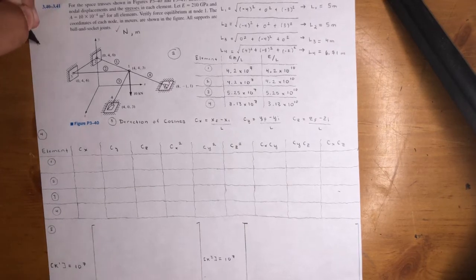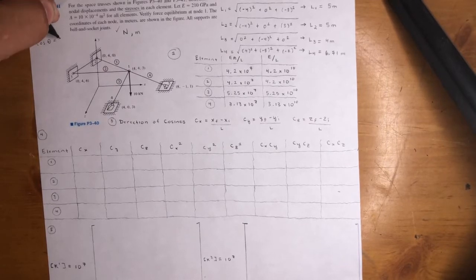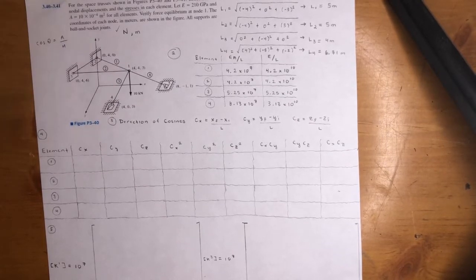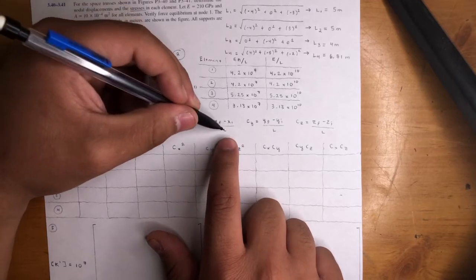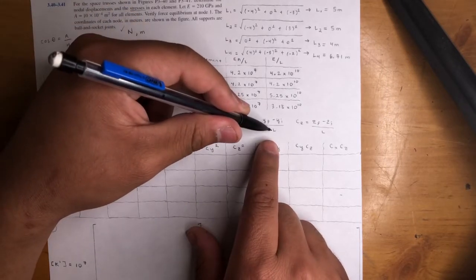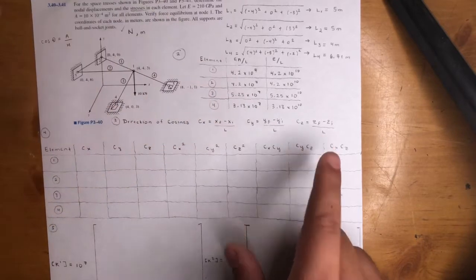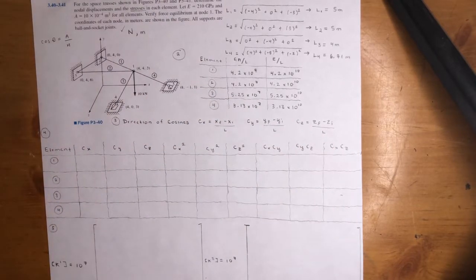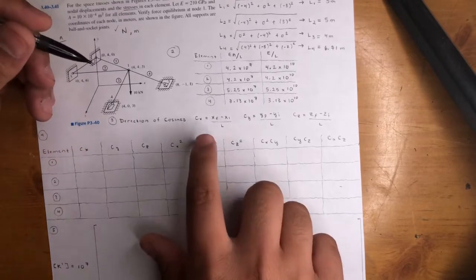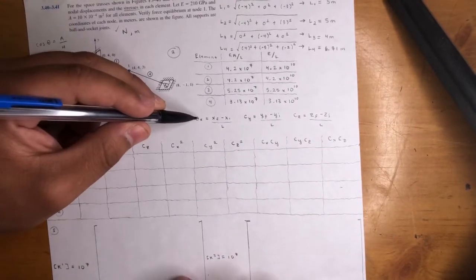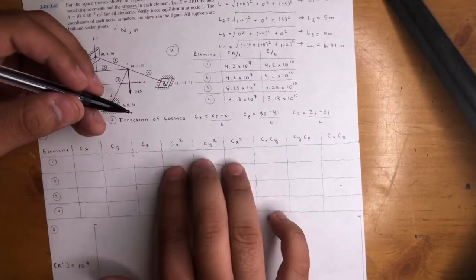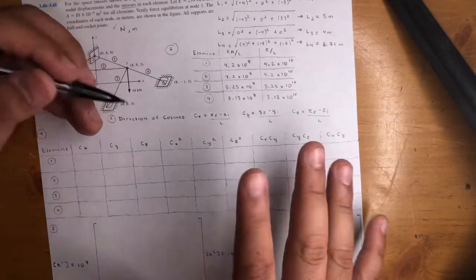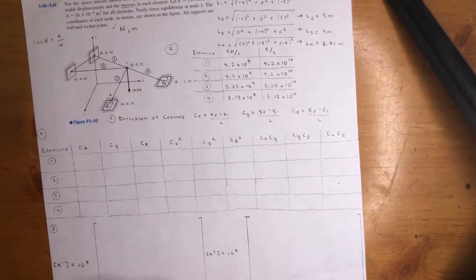So you know how cosine of theta is equal to adjacent over hypotenuse? That's all it is. You could either use the angle, or you could just do A over H, and that's exactly what they're doing. So they're getting the X component divided by the hypotenuse, the Y component divided by the hypotenuse, and then the Z divided by the hypotenuse, and that's all it is. So it's pretty much the same thing if you really think about it, but just follow the formulas, you'll be all right. Use these formulas, CX, CY, CZ. You fill it up here, then you square them, then you multiply them with each other. That's all it is. Okay, so let's go ahead and do that.